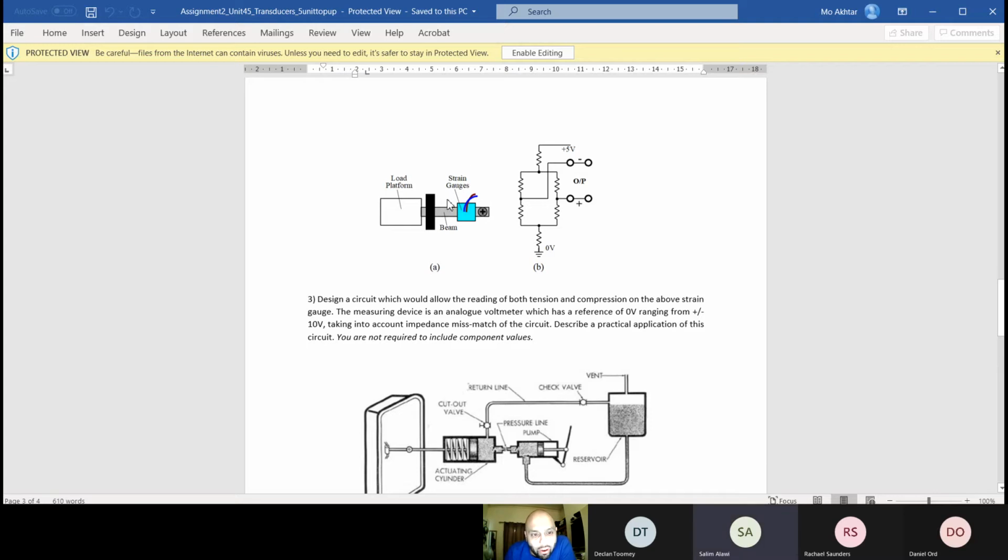All right, what have you got here? You've got a pressure sensor, and you've got a Wheatstone bridge. You've got to redraw the circuit to connect the pressure sensor in a Wheatstone bridge. So you've got to put that pressure sensor into the correct input of the Wheatstone bridge. This is the output here, okay? So you're going to get an output here within the range from the measuring device and analog.